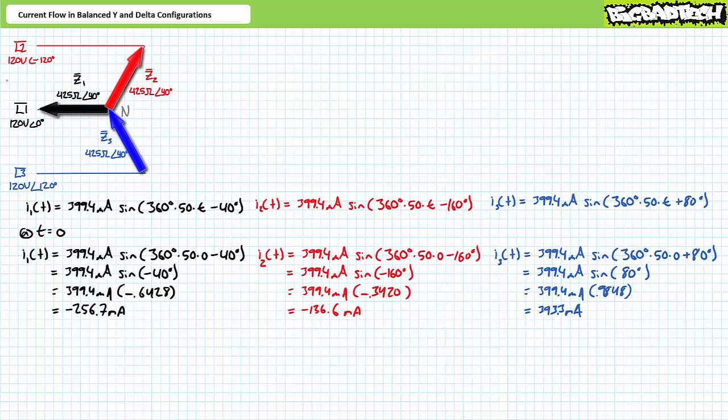256.7 plus 136.6 equals 393.3 milliamperes, proving that what comes in has indeed come out. At t equals 0, I like to visualize line 3 dumping 393.3 milliamperes of current into the balanced Y through impedance element Z3, and all 393.3 milliamperes drains out of the Y through impedance elements Z1 and Z2, more of which flows through Z1 and less through Z2.